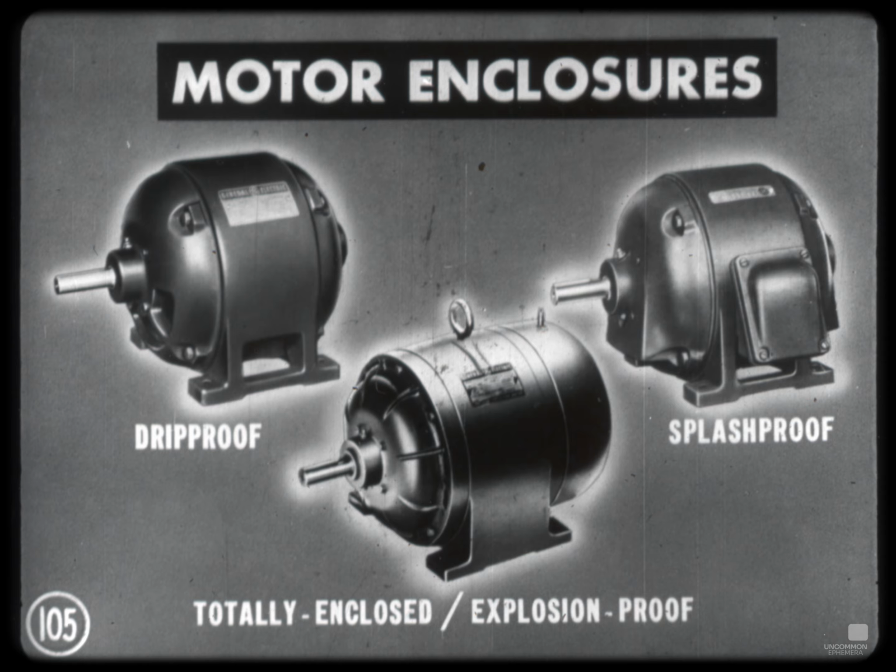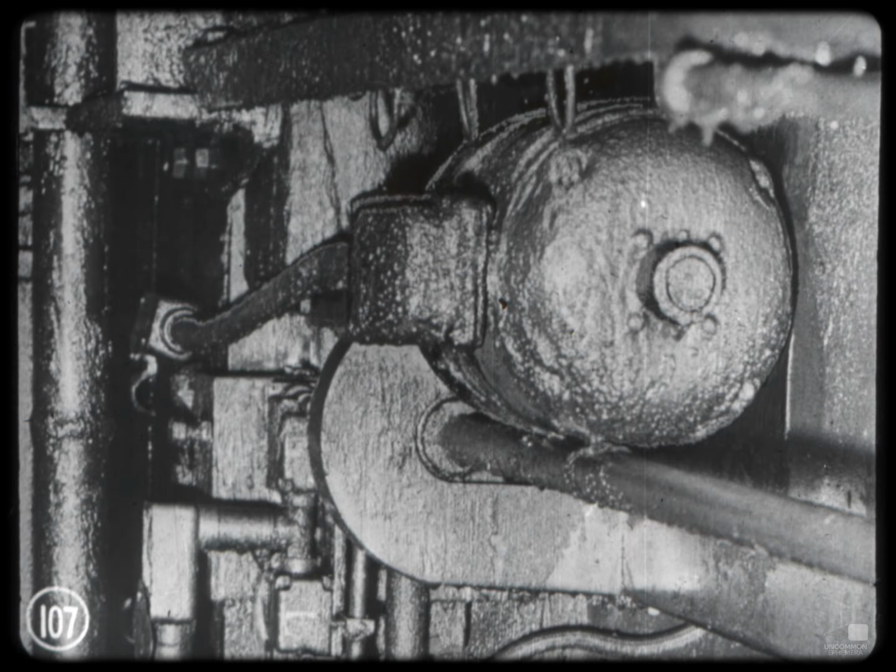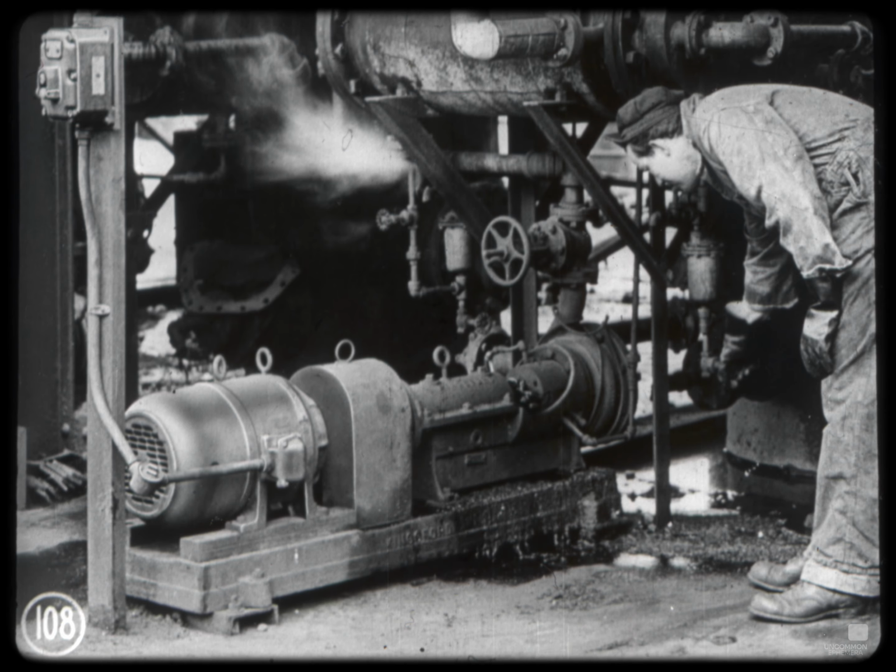One of the enclosed types, on the other hand, is often necessary for extremely dusty or dirty locations or for hazardous atmospheres. Through less maintenance and greater safety, such enclosed types often can save the initial extra cost in the first year of operation alone. When the motor and control are close together, the control always should have the same protective enclosure as the motor.